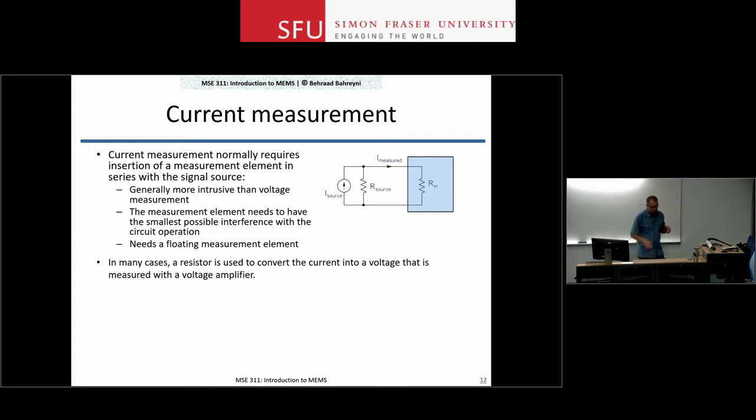So here's one example. Let's say you have a high voltage power line where kiloamps of current flow through that line. If you insert a 1 milliohm resistor in that line, you are going to produce many, many volts across that resistor, right? But getting a 1 milliohm resistor is not that easy. We talk about contact resistance and things like that very soon. So you're going to get a 1 ohm resistance instead. But with 1 ohm and 1 kiloamp, you're producing so much voltage. And then also you're putting so much power through that device.